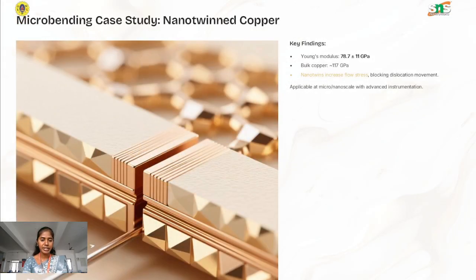Next, the micro bending case study of nano twinned copper. Key findings for nano twinned copper: the Young's modulus of nano twinned copper is 78.7 plus or minus 11 GPa, whereas bulk copper has 117 GPa.